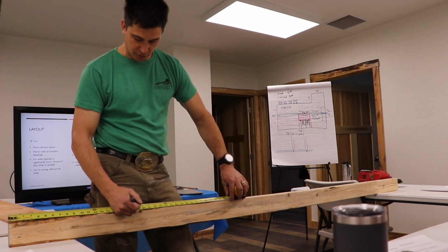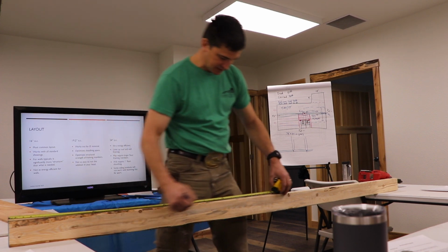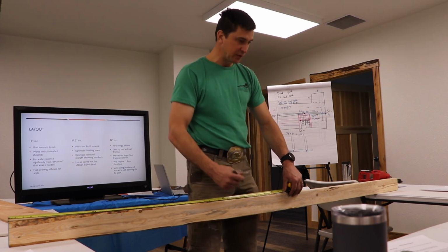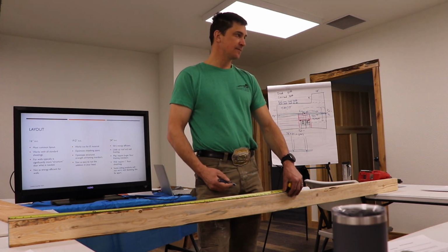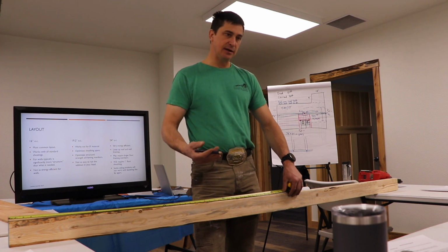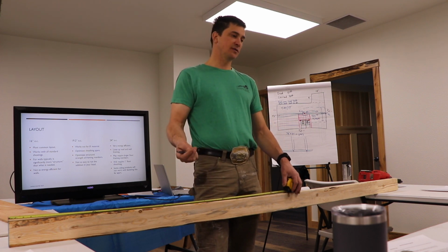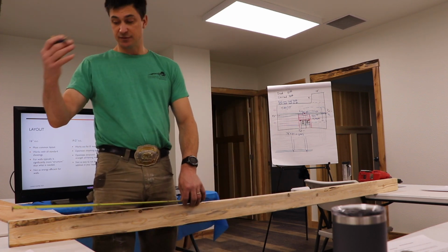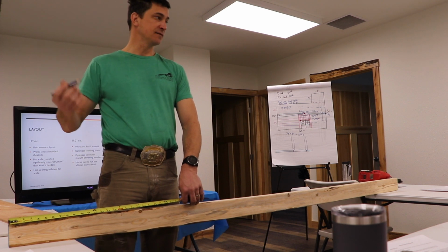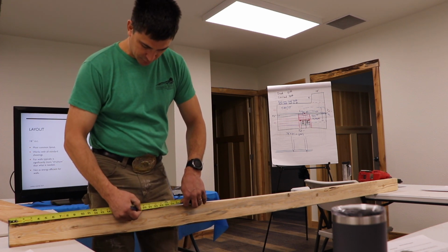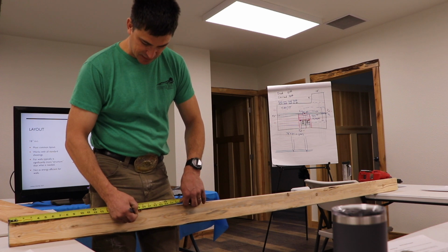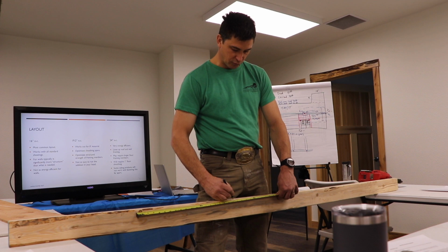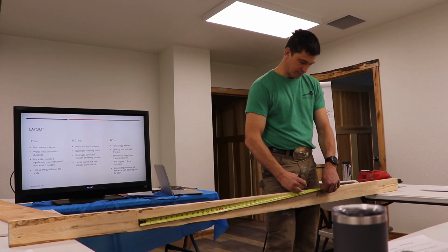You're not going to be able to go, okay, 7/16, but then you get out here and you're at 38 and halfway between 3/8 and 7/16. So generally, most of the time, if you're using the 19.2 layout, just because I'm not that fast at my math on the fly, I'll go to our 7/16. I'll drive a nail in there and hook, and then I can go right on my diamond mark.